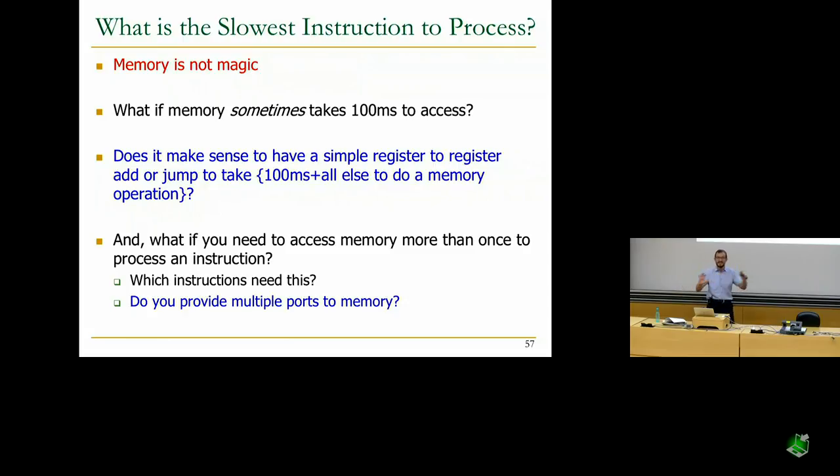Remember, we're doing everything in a single cycle. You should have all of the combinational signals stable for the entire clock cycle for the load word to execute, which means that you should be accessing the memory to get the instruction all the time during that clock cycle. Also, you should be accessing memory to get the data. So you definitely need 2 ports.